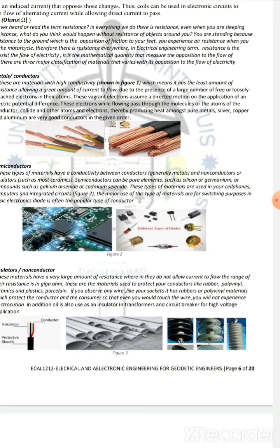You cannot just hang the line on a tower, because your line is metal, therefore it is also a conductor. In order to hold the line, you must have an insulator connected to the tower and then connected to the line. Sir, does your insulator still conduct? Yes. We have leakage currents that break down your insulators. So when you use an insulator on a line, there should also be a computation for it. Okay?